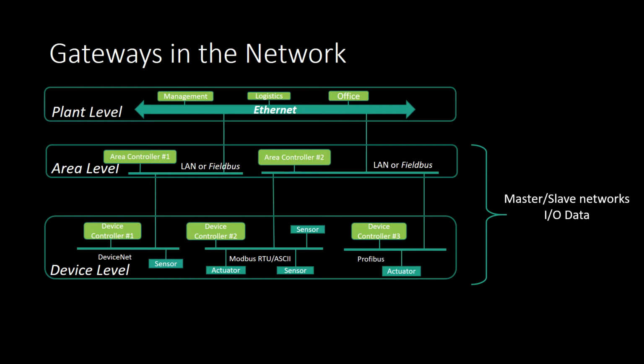It is possible for a controller, such as a PLC, to act as a client, a server, and an I/O master within a network. The I/O messages will have priority over client-server data as they are set as time-critical, whereas the client-server data will be sent and received as the processing power becomes available.